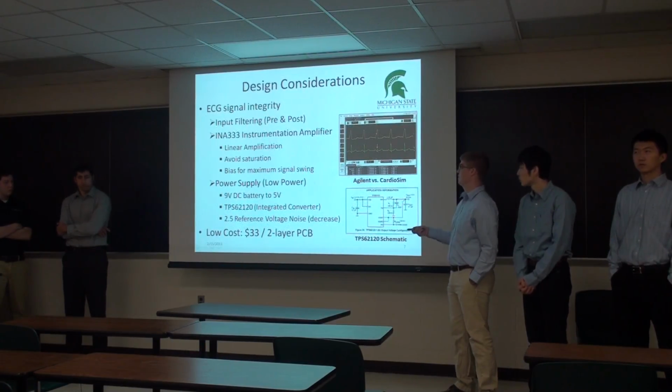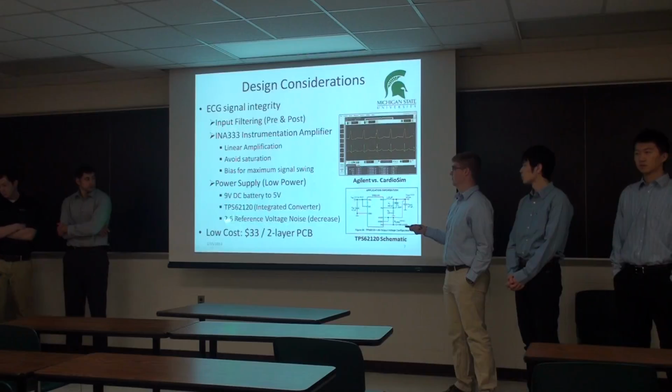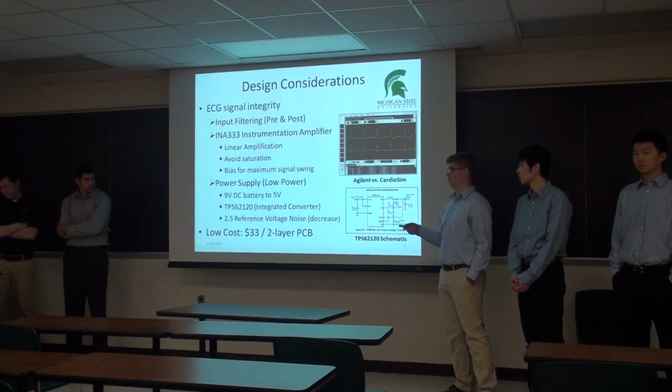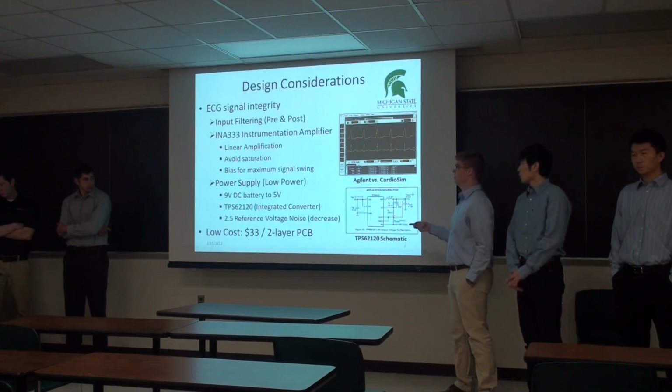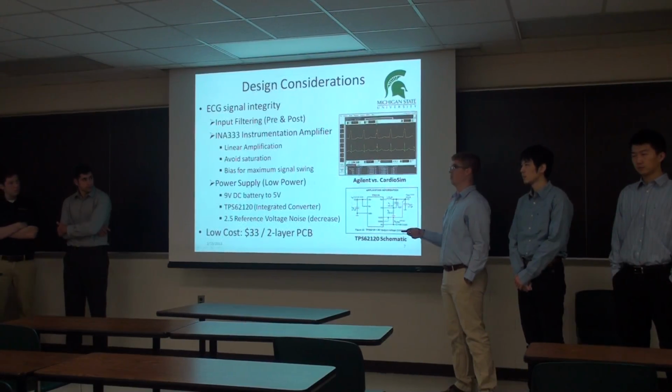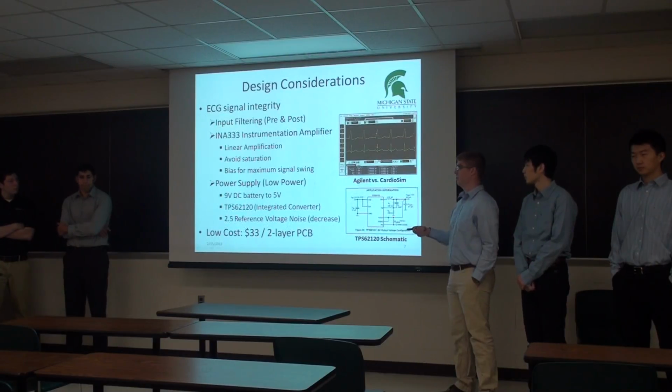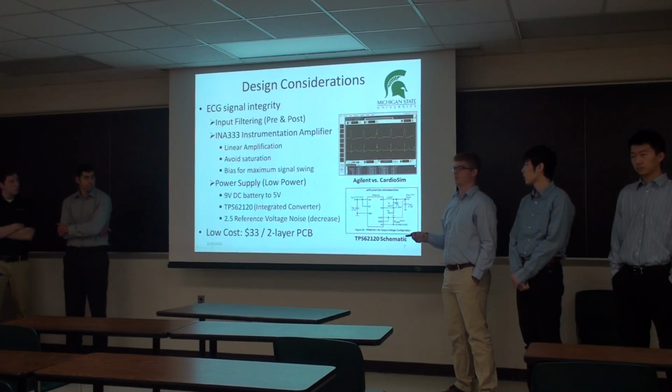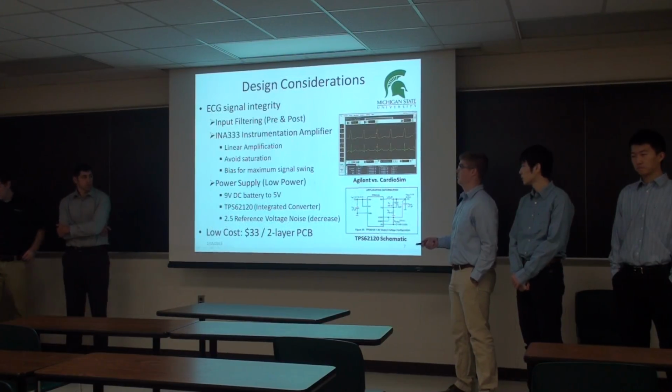Because of this, this 2.5-volt reference is what our input signals and our output signals are riding on at that DC level. So any noise on this 2.5-volt reference voltage will carry through to our output signals. And in lab already, we've been experimenting with different ways of filtering that signal and getting a clean reference. And it's just further shown that it's really important to have a clean reference.